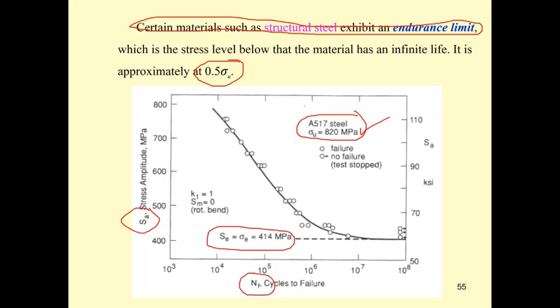However, there are welded joints in structures that are prone to fatigue, because when you weld a structure, the weld is always very hot, and some workers just spray water onto the weld joints. A lot of the time the weld joint cracks, and that is a starting point of fatigue.